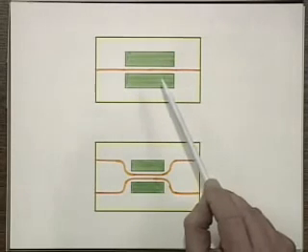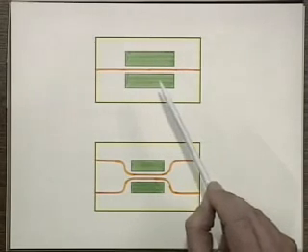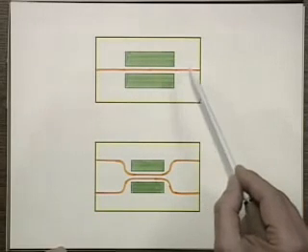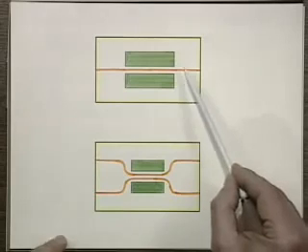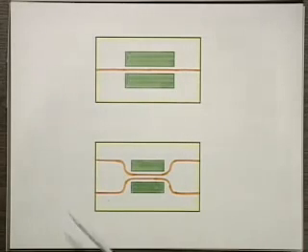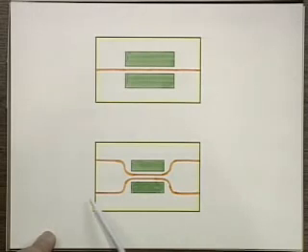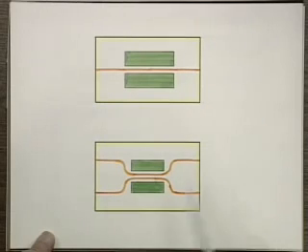Now, if you want to use it as a coupler or as an intensity modulator and so on, you have to combine several waveguides, two waveguides together, and then you can create a coupler. Here I've chosen this example where I have one guide that looks like this and the other guide that looks like that. If I put light in one arm, normally it would come out over here. But depending on the closeness of these two cores, some light will be coupled into this other side and come out over here. So this is, let's say, a fixed coupler.